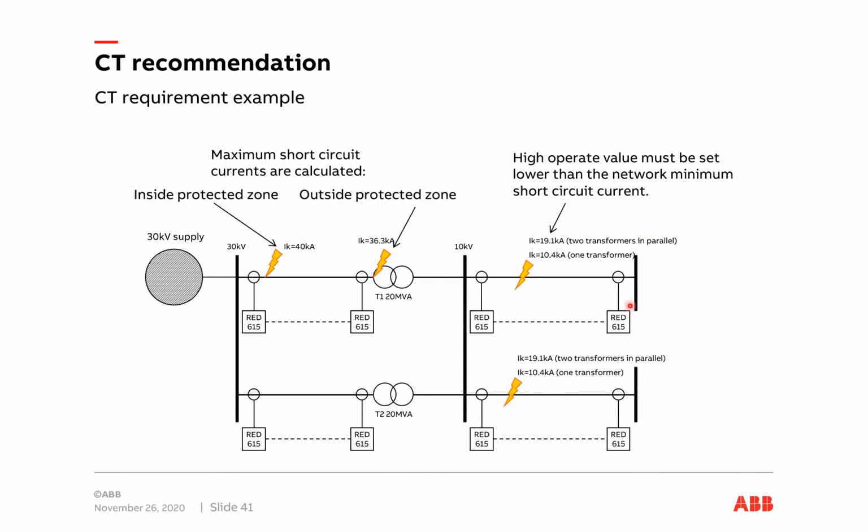Now, here I have one example. What I would like to bring up here is that it's not enough to look only at the part of the line that we are protecting when defining the settings and the CT recommendations for line differential protection. We need to look at the overall picture.